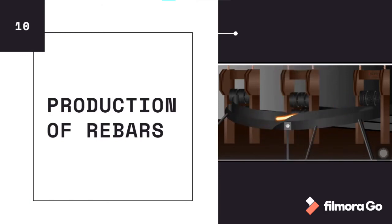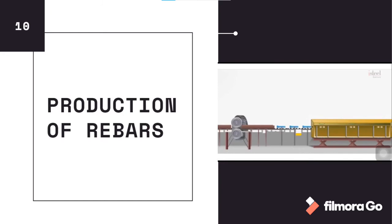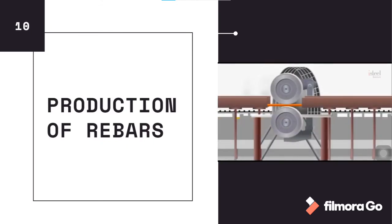customers' construction needs. Another critical part of the manufacturing process is that of water quenching and tempering, where the finished diameter bars are heat treated to give the desired properties. To make sure that every bar spends the same amount of time in the quenching chamber, the bars are guided into it by pinch rolls, thereby giving consistency of properties across the bar and straightened bars.